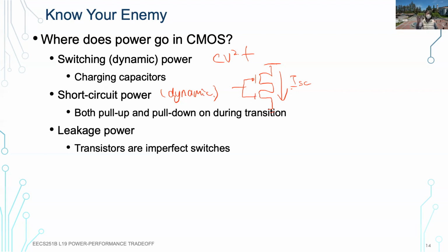Yeah, related. As Ken mentioned, the circuit is actually so fast now, it's very unlikely that both NMOS and PMOS are on. It's also related to voltage, right? So VDD here. If the voltage is very low, to have both on, the gate voltage for both PMOS and NMOS needs to be bigger than the threshold voltage. Now the threshold voltage is relatively constant, and VDD is getting smaller. So it's very rare to have a voltage that is able to turn on both PMOS and NMOS.